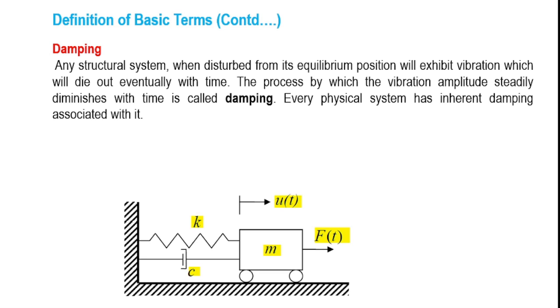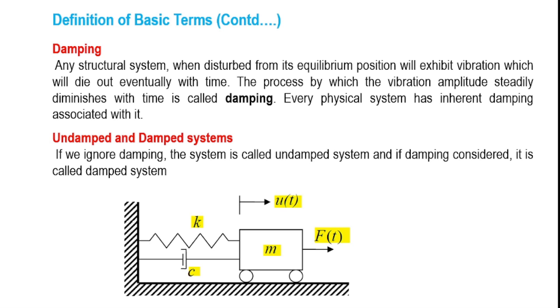And remember that damping can take various forms. In its simplest form, it can be a viscous damping. And when you go to higher levels of energy dissipation, for example, you want to study the response of a system under strong excitation of ground motion, or maybe under a blast load, the damping takes various forms. For example, it can be a hysteretic damping, it can be a radiation damping, it can be a geometric damping. So there are many versions of damping, and we'll go through this in a later session of our presentation.